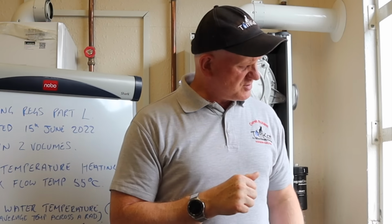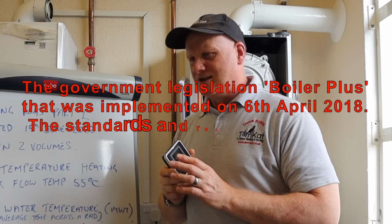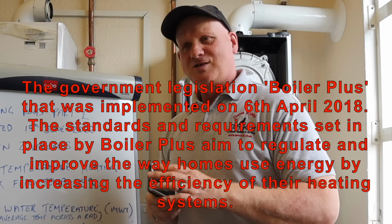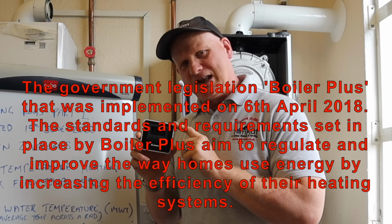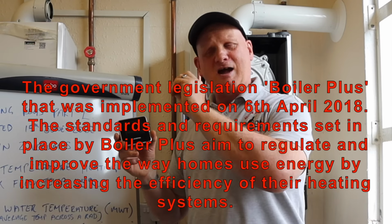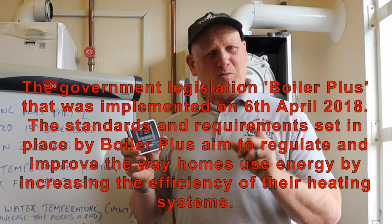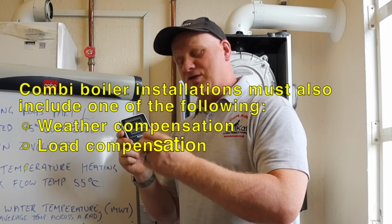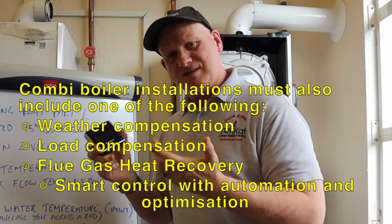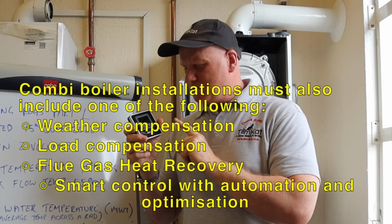Other considerations, which nobody seems to be mentioning, is your room thermostat. You should have a room thermostat to comply with the laws. So from 2005 it's been law that room stats need to be installed, and now with all the ERP directive they have to be not just smart thermostats but be able to know what the temperature inside the house is to adjust the flow temperatures on the boilers. So the room stat is incredibly important.